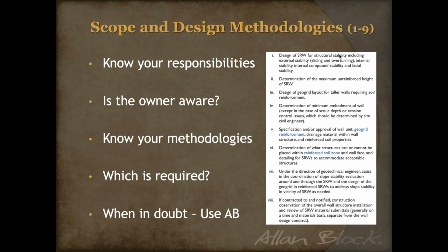Moving on to the methodologies. There's a ton of methodologies out there. You've got AASHTO, you've got NCMA, things like that. Not all projects or states or areas require the same methodologies to be used for their wall design. So it can get a little confusing sometimes, but it's important for you to know what's required for your project. That way, you avoid designing in one methodology and the project requiring a different one, and the design having to be redone.